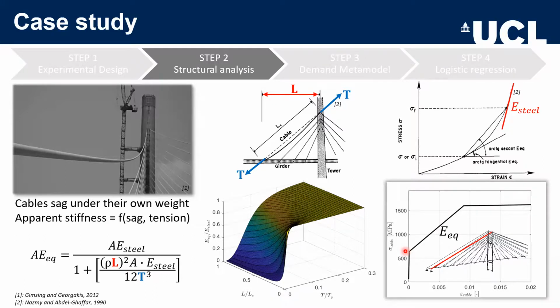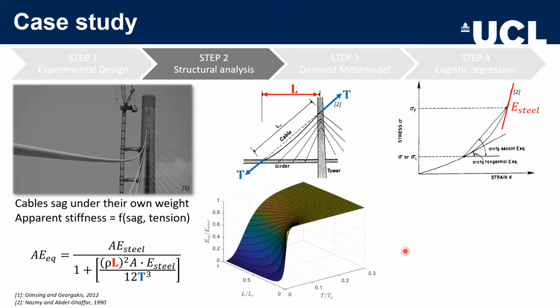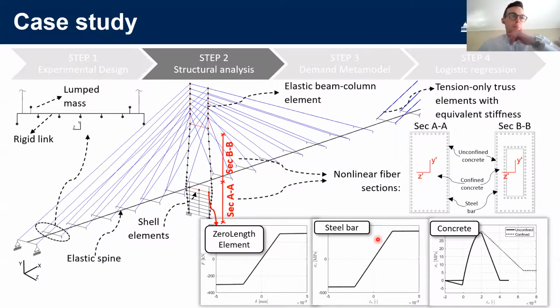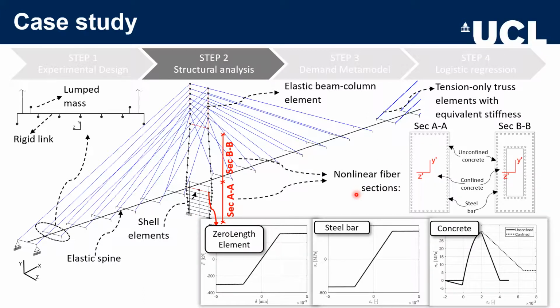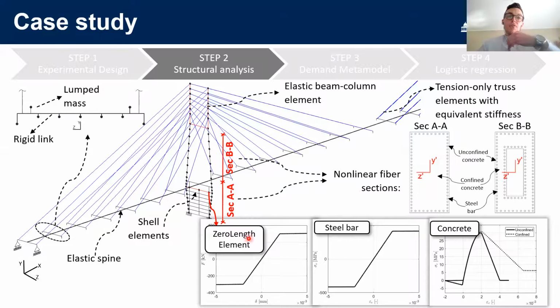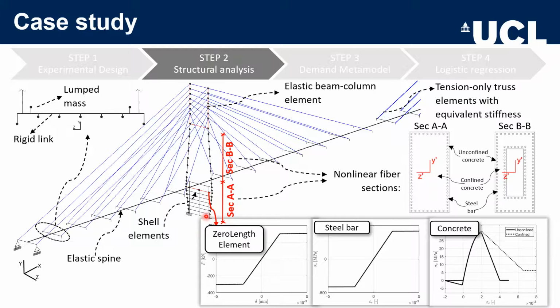Perfect. Can you tell me how you're applying the earthquake load as well, and where you're applying it? I might have missed it. I'm applying the earthquake load at all the fixed points of the structure. So there will be an earthquake load here, earthquake load at the base of the two towers. Okay, only in X direction? Both the X and Y direction. And Y direction. Okay, you're using the up-down component of the earthquake?